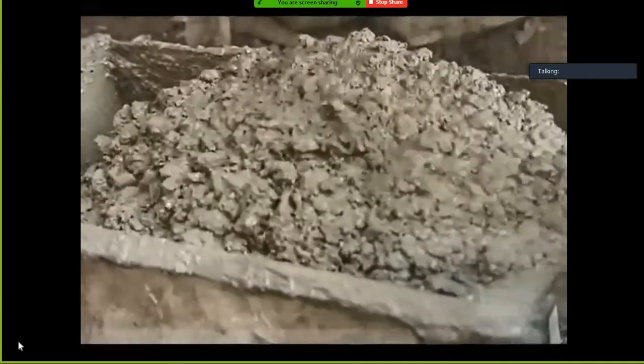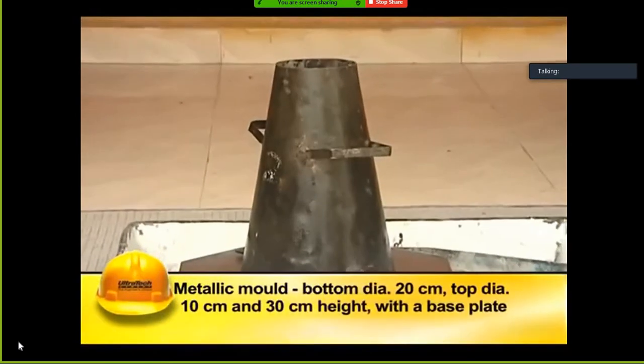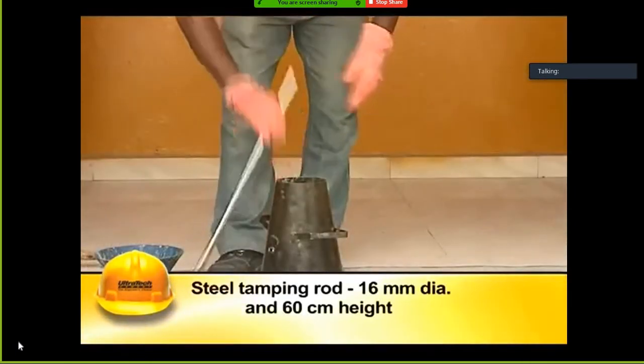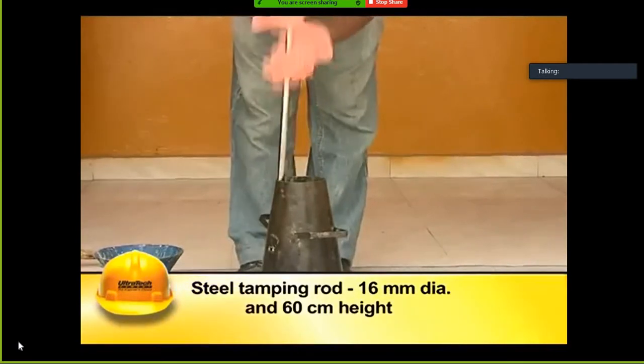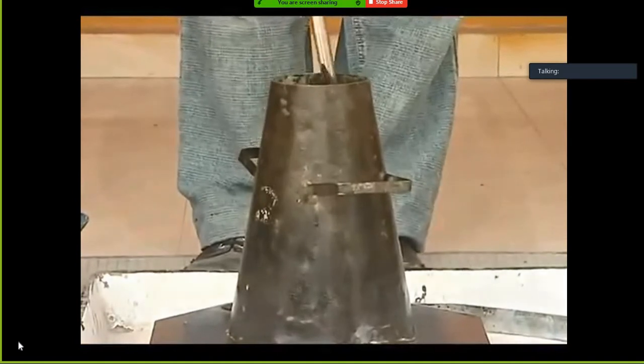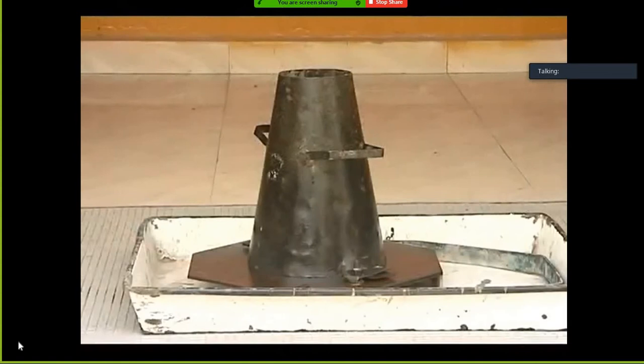The apparatus for conducting the slump test essentially consists of a metallic mold in the form of a frustum of a cone with a base plate. A steel tamping rod of 16 mm diameter and 60 cm height is to be used for compacting. The internal surface of the mold should be thoroughly cleaned of moisture and any hardened concrete before commencing the test. The mold is placed on a smooth, horizontal, rigid and non-absorbent surface.